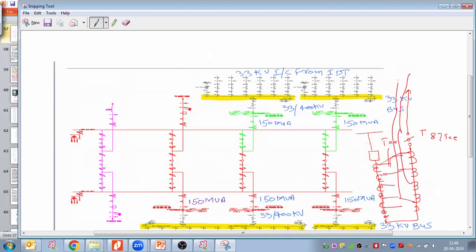So if your client is asking for a particular separate T differential protection, in that case, at the exit point, one more CT you have to take. But that CT again will come before the CVT. And I think I have to check once whether we take this CT before the isolator or after the isolator. I will check the CT.